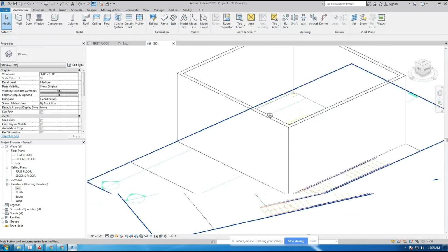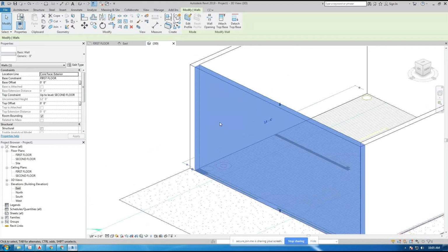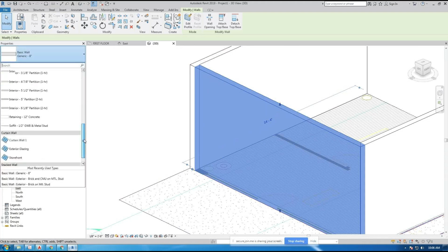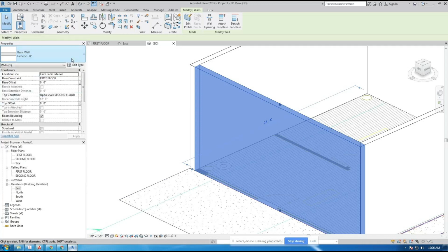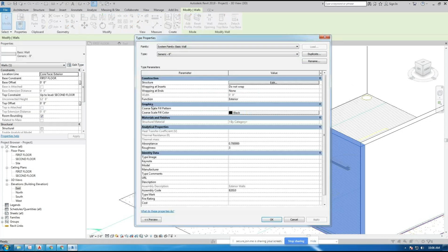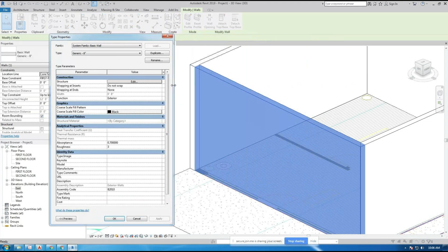So I'm working in Revit. I click on this object. What's it made out of? That information is stored here under Edit Type. Edit Type gives you information about this wall. This type of wall, again, the types, these are all types. I'm working on the 8-inch type right now. So Edit Type means edit this type of wall, which is edit the 8-inch wall, because that's the type I have currently highlighted here. And here's more information you can manipulate in Revit regarding that wall.